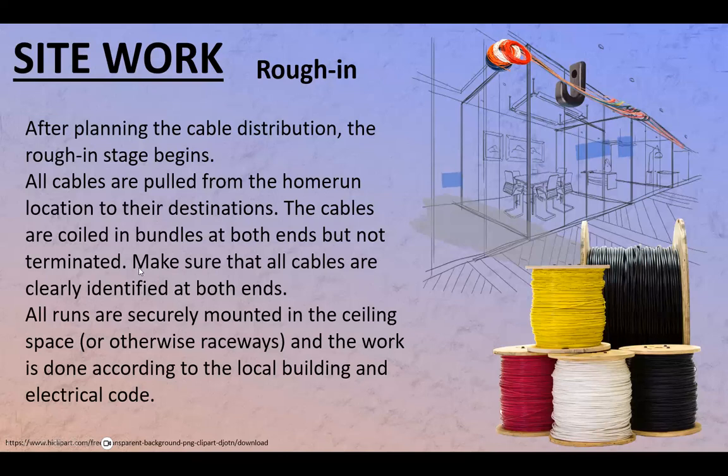Love you. All right. Anyways, make sure that all the cables are clearly identified at both ends. Couldn't say that enough. Said it a million times. All runs are securely mounted in the ceiling space, or otherwise raceways, and the work is done according to the local building and electrical code. And make sure that the wires are left in a way that nobody's going to step on them, because there are going to be other trades. So it's in your interest to secure those wires, so that there's the least amount of damage possible by other people doing other jobs around the construction site. Right.